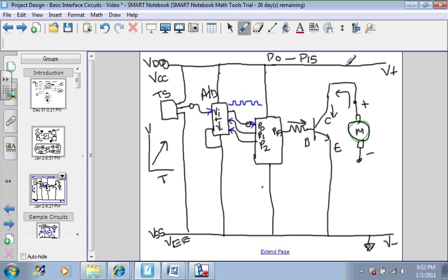Well, you could use the same power supply up here, but you have to be sure what is the value of these. I believe for my design, all of these are 5 volts. However, I normally use a 12-volt motor. This is a situation where I need two power supplies.